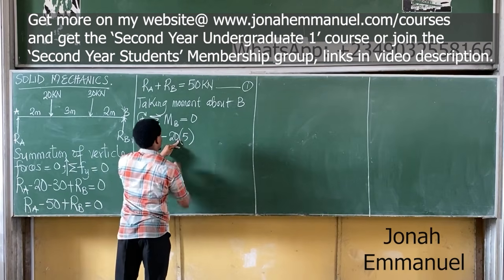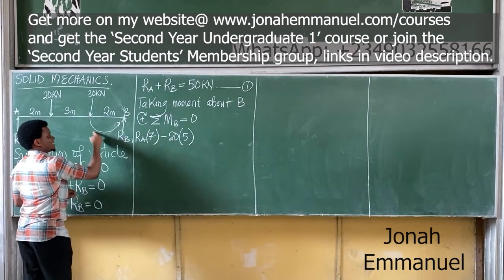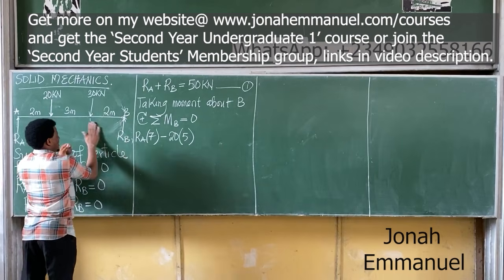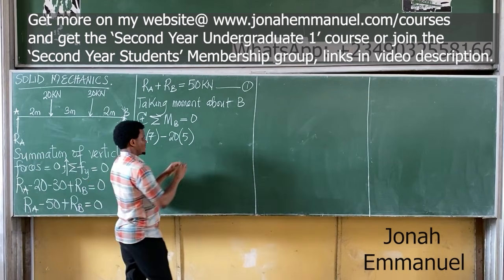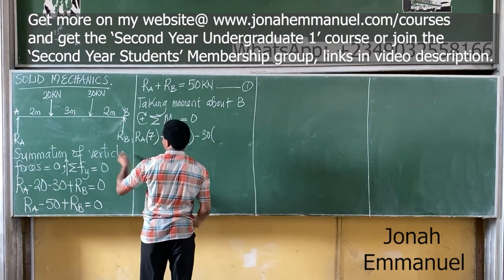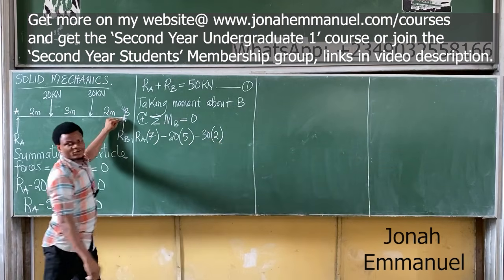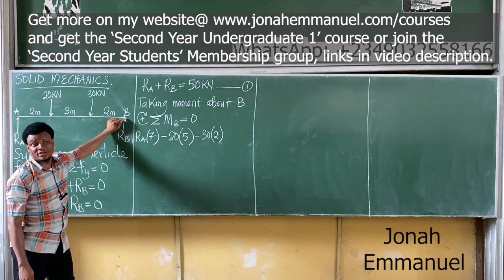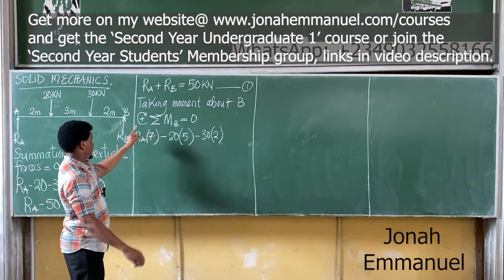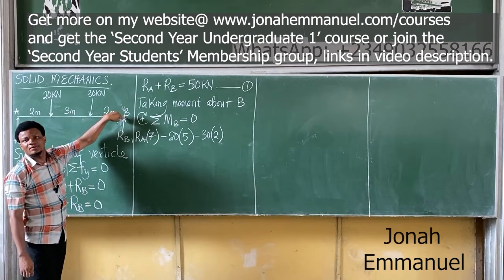Next up, this force here, going down this way. Look at this movement here. Clockwise or anti-clockwise? It's anti-clockwise. So it becomes what there? Negative. Minus the value there, 30. Distance from here to here, 2. Do we include RB? Do we include RB? If you want to put RB, what's the distance of RB?